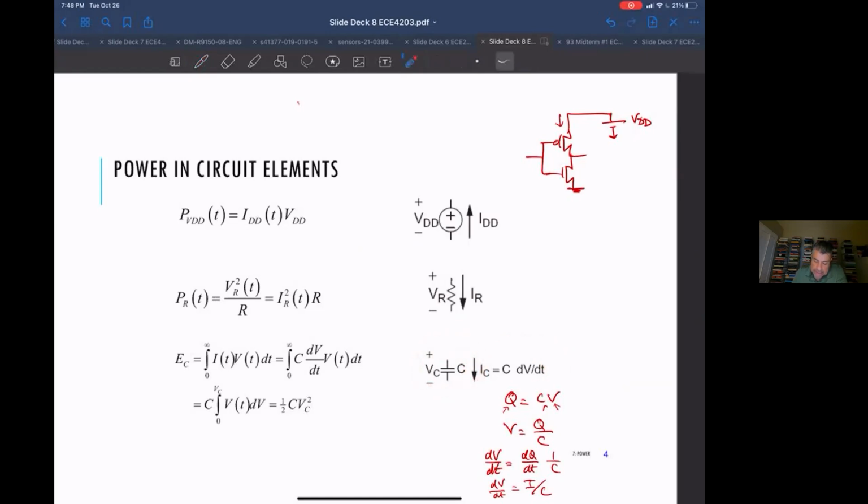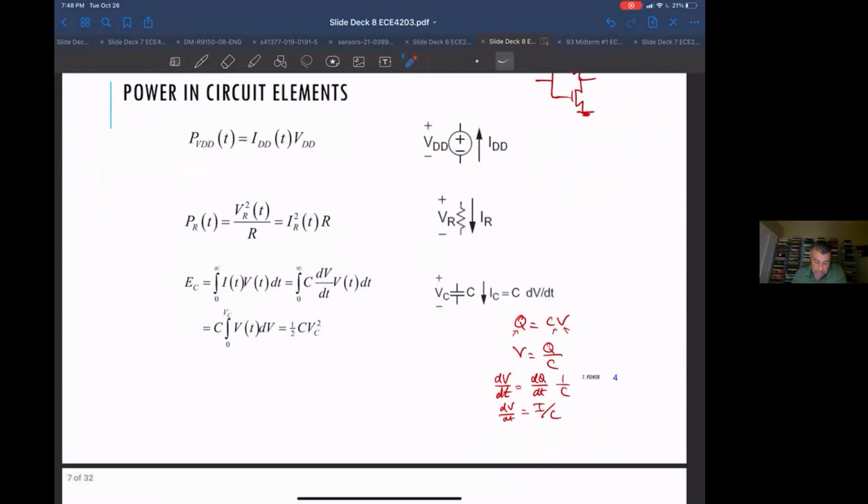But it's not a continuous power consumption, it's an energy, because both current and voltage are changing as you're charging this thing up. For a single time where you charge or discharge this thing, you're saying what happens if I look at all the current and all the voltage change while I am charging or discharging this capacitance. So that's why in time you're going from 0 to infinity, because you're assuming it's one time where I'm charging this thing, and theoretically you could do it forever. The voltage will keep ramping up, and the energy going into the capacitor will keep going up. So that's why you're doing the 0 to infinity thing when you're integrating with respect to time.